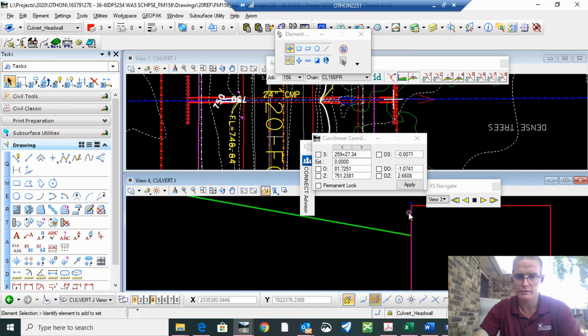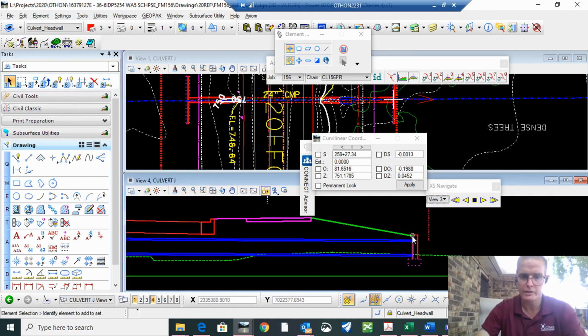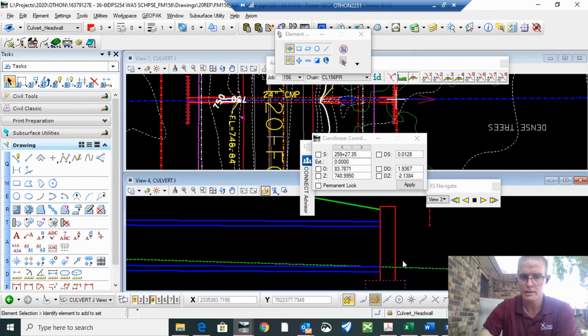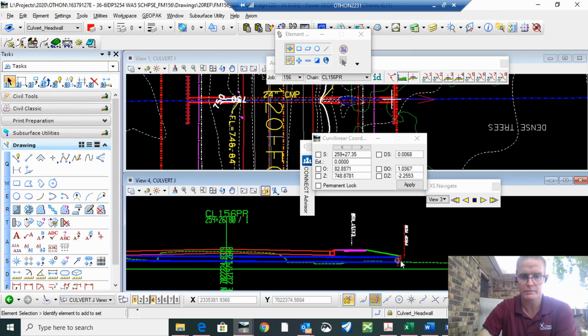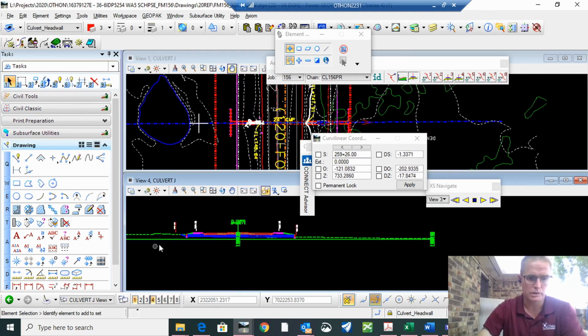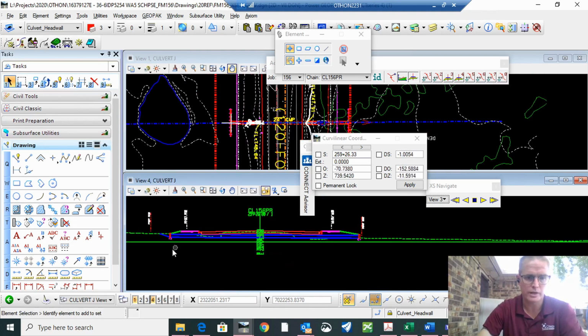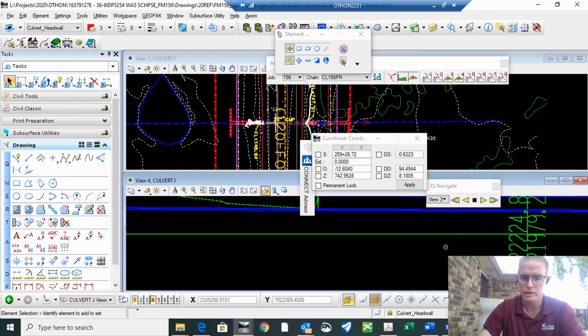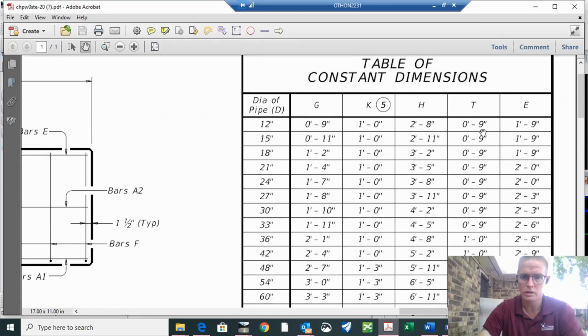And look, we're good. We don't have to move the head wall because the grading fits just fine. And that's it. So this one is good in plan view. This one needs to be moved out. This is a similar exercise all the way around, but we know that this head wall is 3 foot 8 inches, basically 4 foot.